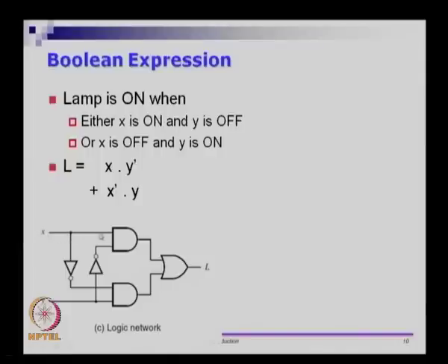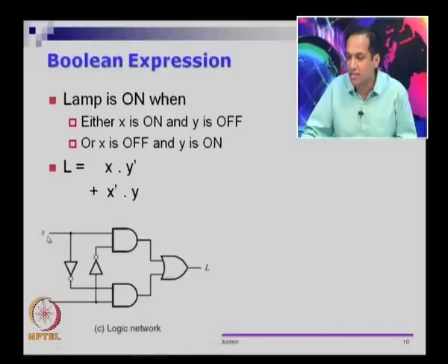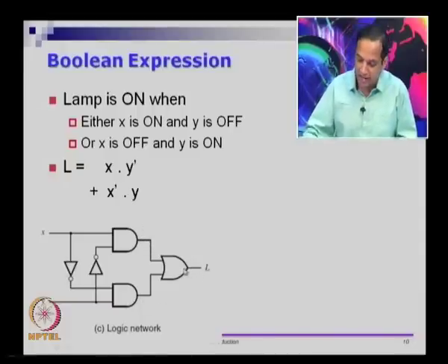So this line goes as X and this comes as complement, and if you notice there is a filled circle here. In electrical circuits we use that to denote branches, right. You probably know that from your basic electric circuits, that when you have a dot on a line it means that you are branching. So X is branching here and here, this line comes as X complement, this line goes as X. Similarly for Y, this line goes as Y, this line goes as Y complement. This one is for X and Y bar, this is for Y and X bar, and that is L.